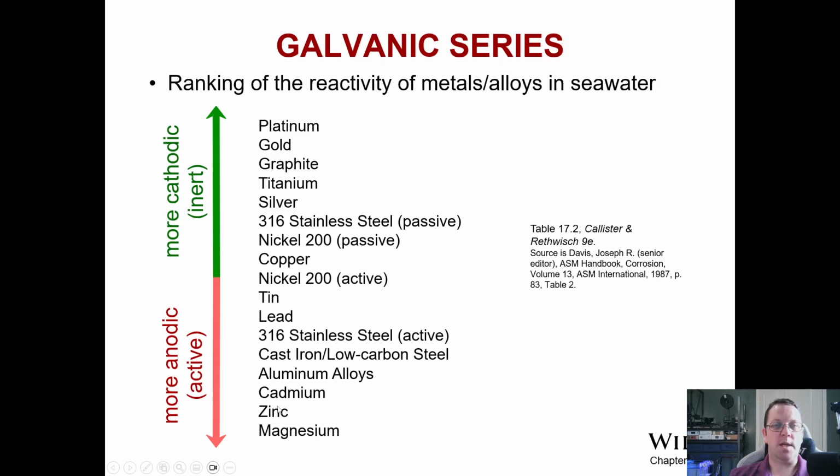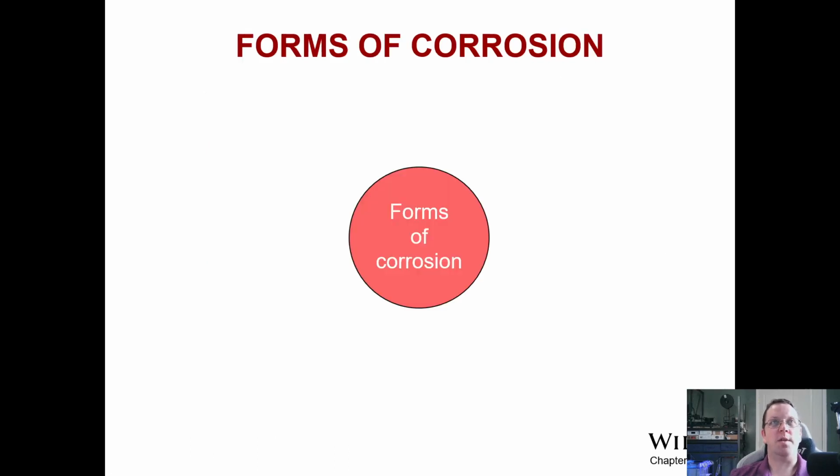This is why we use zinc as often a sacrificial layer, because it's much more cheaply available, and it tends to work very well without hugely compromising the mechanical properties in the way that something like magnesium might. It also doesn't have the same degree of dangers of igniting as something like magnesium does. So there's a lot of application and range to what this says. So there are a lot of different forms that this can take.